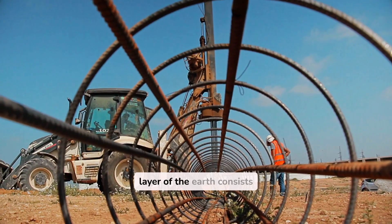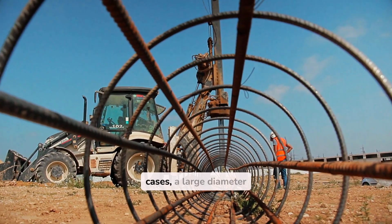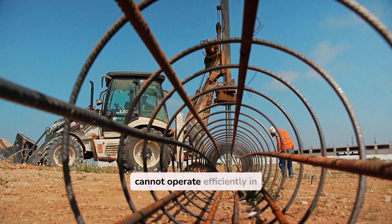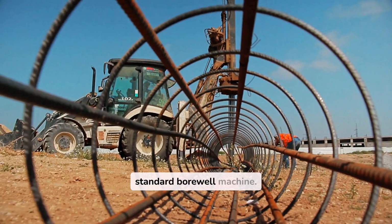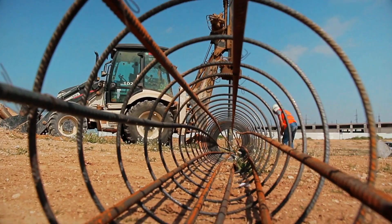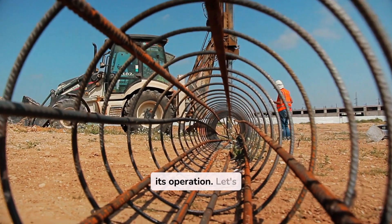Usually, the top layer of the earth consists of soil or weak rock. For example, let's assume the first 50 feet is just soil. In such cases, a large diameter borehole is created initially. This large initial hole is not made using the oil rig itself, as it cannot operate efficiently in loose soil. Instead, it is done using a standard borewell machine. Once this initial borewell is ready, a casing pipe is inserted and cement is poured around it. Once the cement hardens, it prevents soil and water from entering the wellbore. From here, the drilling rig starts its operation.